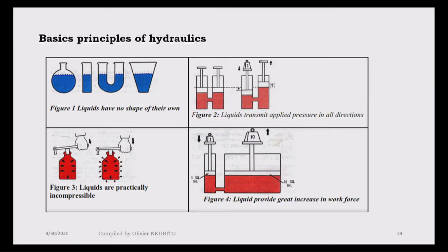Number three, liquids can transmit power. If you link two cylinders, like what I have here, by a pipe, and you fill them with liquid like oil, if you press one piston to move downward, the other piston will move upward. This means you can transmit the applied force.